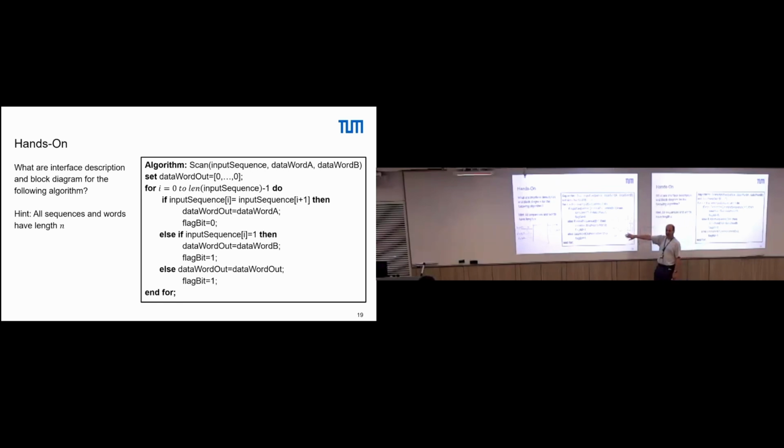Yeah, we need to understand it. And then we try to think this algorithm in hardware. And thinking in hardware means roughly we need to decide what is logic. So kinds of comparators are usually logic, this inversion here is logic. We need to decide what is actually a register or some memory needed. And we decide at which points we need, for instance, things like multiplexers.